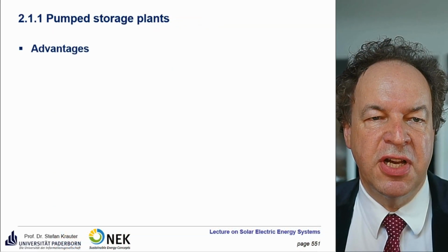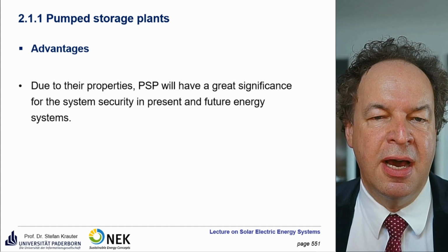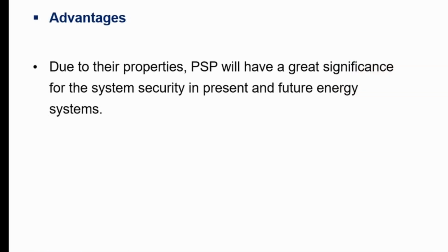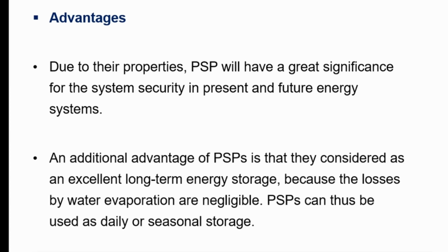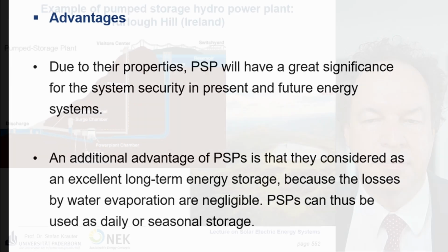So the advantages of such pumped storage power plants are that they provide system security presently, but even more important for future systems. They are also considered as long-term energy storage because the losses by water evaporation are quite negligible. So this can even be used for seasonal storage, not only for daily or weekly storage.